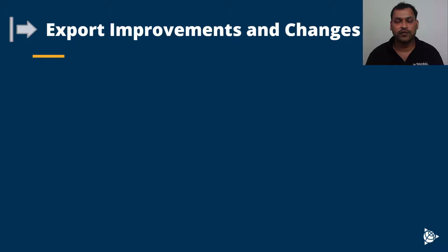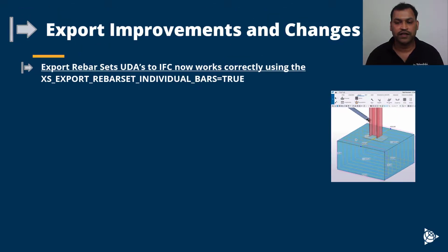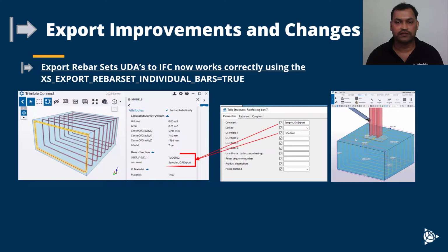Next, we will see the improvements and changes in the IFC export. Rebar set UDAs can now be exported properly to the IFC when the advanced option for rebar set to export as an individual rebar set is set to true.